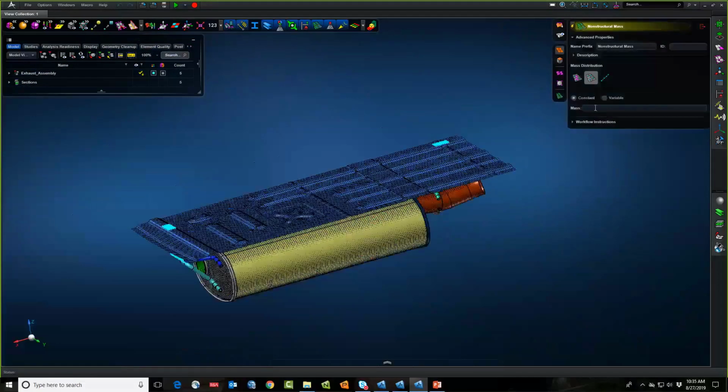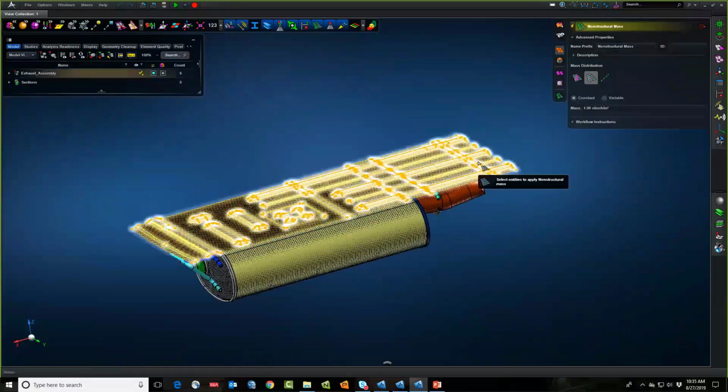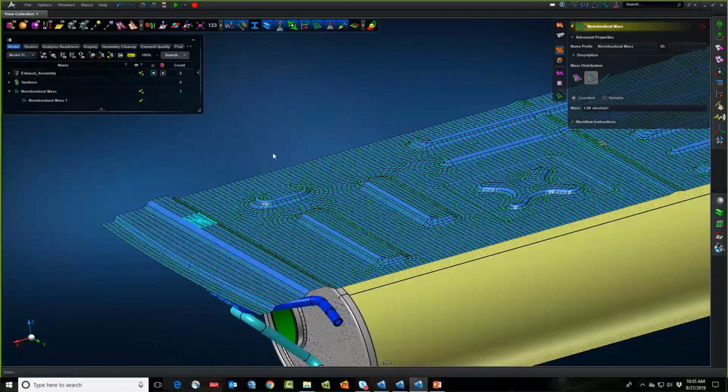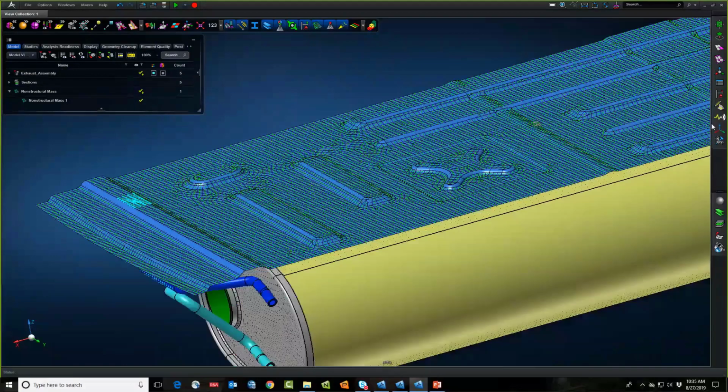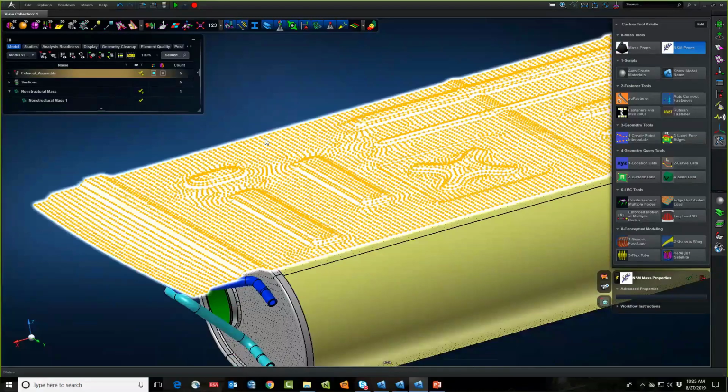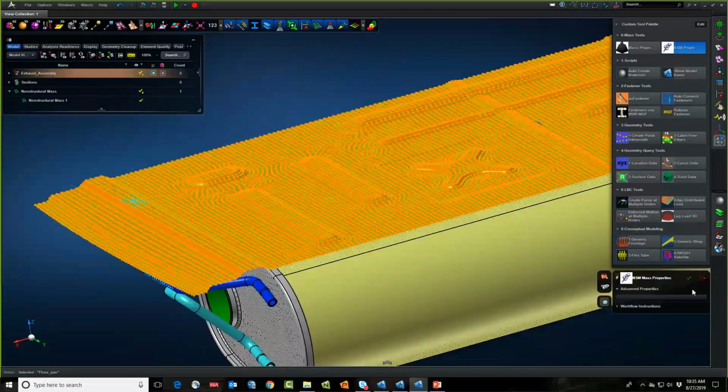So let's just do a non-structural mass per area, all right? And we'll just simply select that surface, and you can see that Apex has put this non-structural mass all over this surface. Perhaps this represents an acoustic lining material. Maybe it represents the carpeting that's assigned here. And what I'm going to do real quick is check to see what the non-structural mass is for this part. I entered in 1 per unit area, and of course I didn't actually check what the area was, but I've got a quick utility I wrote that'll quickly tell me what the non-structural mass is that's been assigned to this floor panel.